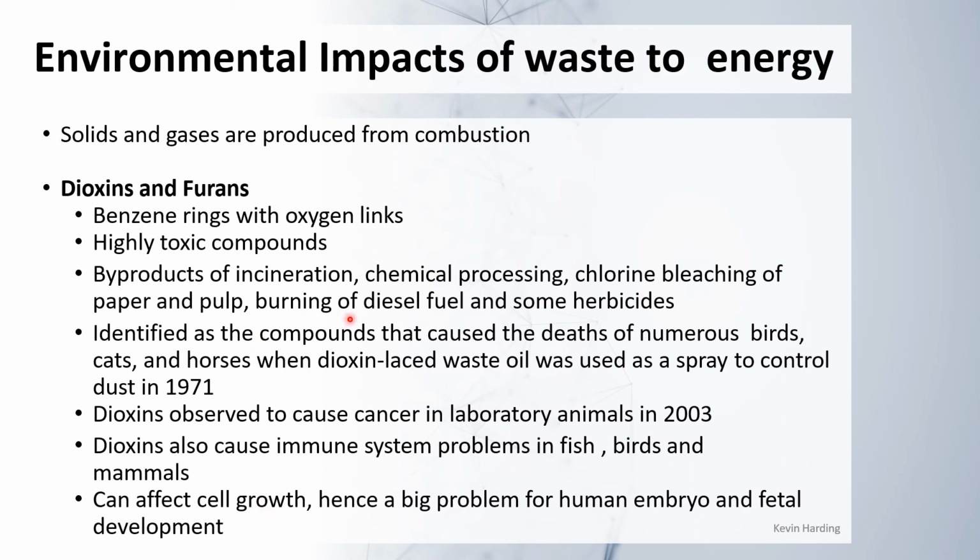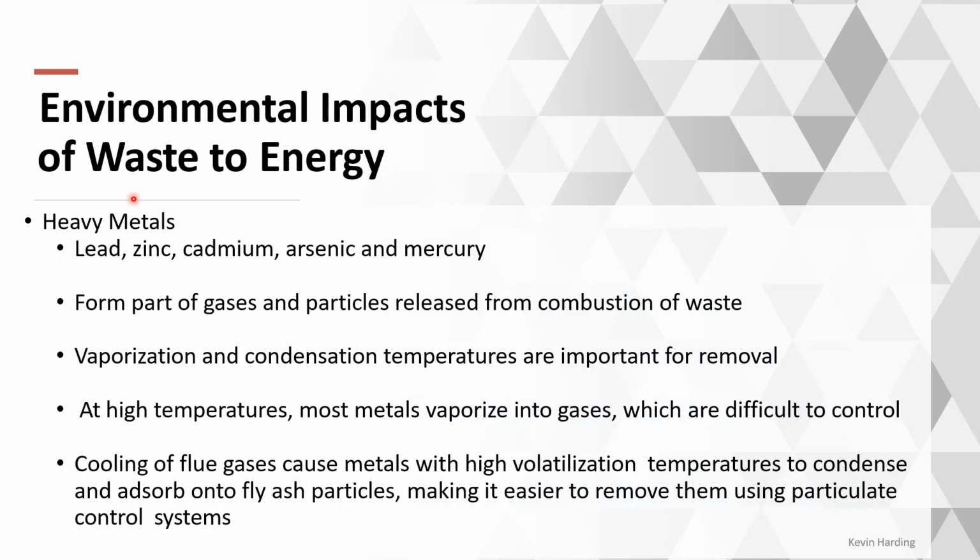Excuse me. Okay, so there are some issues with burning. There are also other problems. The first one being that it can concentrate the heavy metals. When you had a large portion of solid waste before burning, after you've burnt, all of the heavy metals are now in one single source. This could be a good thing because now you can control it, but now you have a concentrated heavy metal stream which you need to do something with.